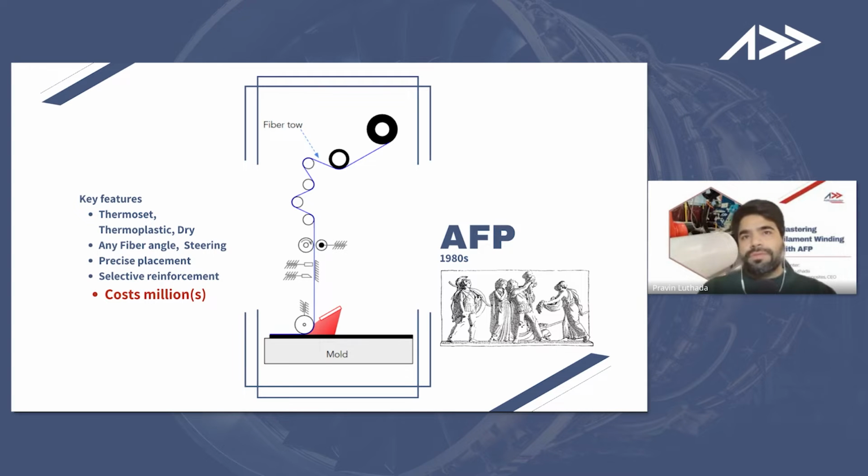Thus, you're able to automate for more complex geometries, complex from the ATL point of view, which is a kind of analog to what filament winding looks like. In addition, we have cut and clamp ability. And heat got added, I think around the 1990s, to increase the tackiness in this type of AFP system.